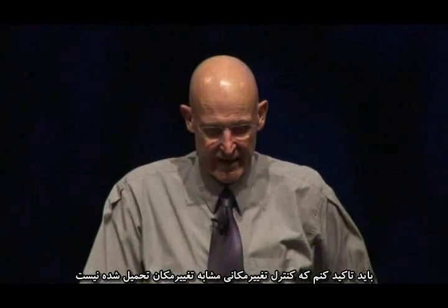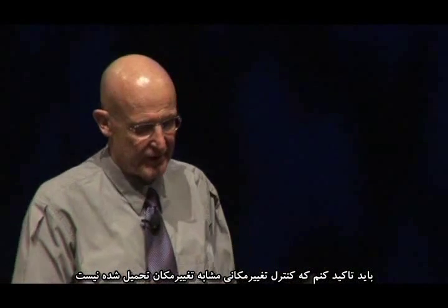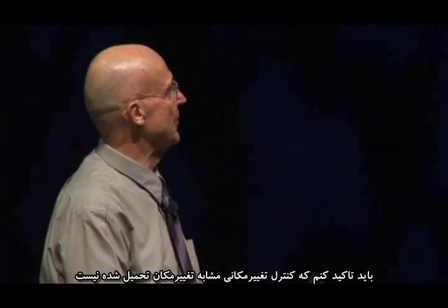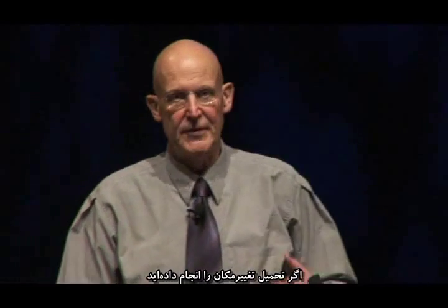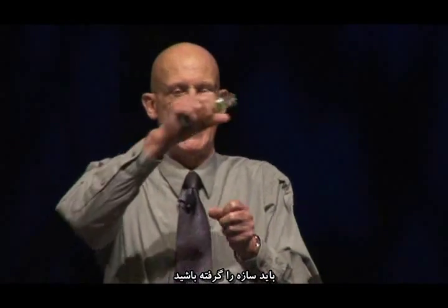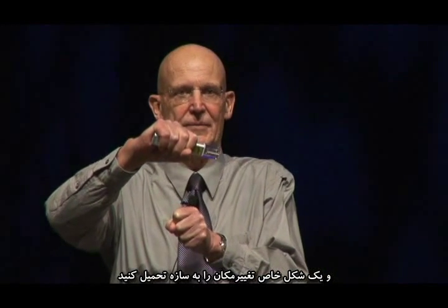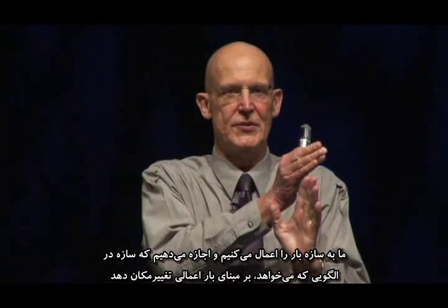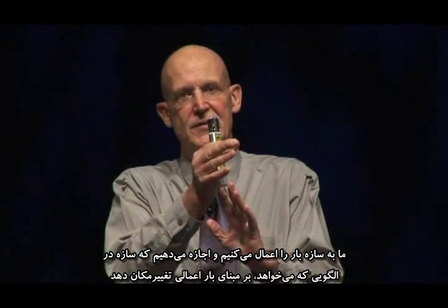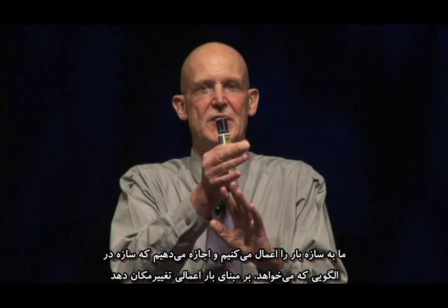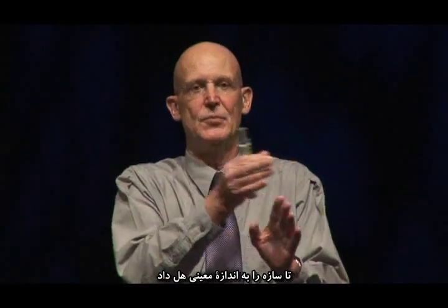I do want to emphasize that displacement control is not the same as imposed displacements. If you did imposed displacements, you would grab the structure and you would impose a particular displaced shape on the structure. That's not what we're doing. We're applying a load to the structure and letting it displace in the pattern it wants to displace based on that load. But we're just going to determine how much load it takes to push the structure over a certain amount, and then how much more load to push it over another certain amount. It's actually easier than imposed displacements.